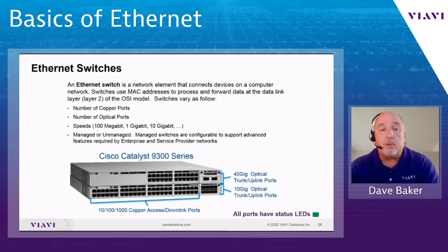Again, these optics are typically inserted into a switch for Ethernet connections, or router, or perhaps a server. But the ports on the switch that support these are commonly called trunk ports, and they're the higher speed ports that connect up to the remainder of the network, at least for edge switches like this to support users on phones and routers. So a given switch might vary in the number of copper ports it has and the number of optical ports and the speeds of them. So this is a work group switch pictured here that has a lot of copper ports on it. So several PCs and phones on a floor or a section of a building might be connected up to this, being installed in a wiring closet somewhere. Whereas the uplinks would be connected up to the core network, to the internet or the intranet in order to provide connectivity to the remainder of the network.